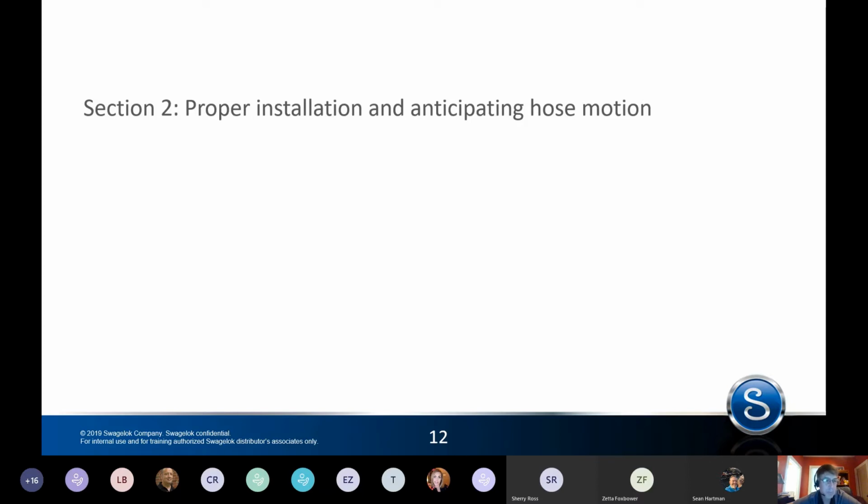Example, around a pump. Yeah, very good. So vibration, we would say, has a very similar effect on hoses that pressure impulse does. It's different reasons, but similar effect. So the best hose for a vibration application is a thermoplastic or nylon hose. The worst would be a metal hose.